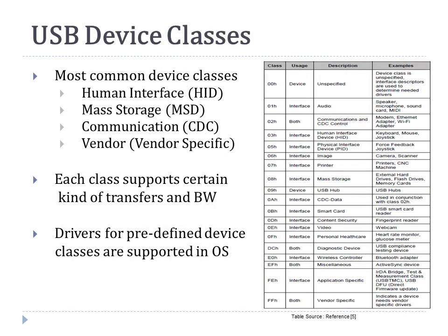Again, there are various kinds of devices. The important ones are HID device, which is a human interface device like the mouse and the keyboard, the mass storage device, like the portable disk drives, the communication devices, like USB connected Wi-Fi routers or modems or Ethernet ports, and there could be some special ones called vendor specific devices. And each device class needs a class driver, as we described earlier. So it has a special class driver which is a part of the device software, and part of it is implemented in the OS.